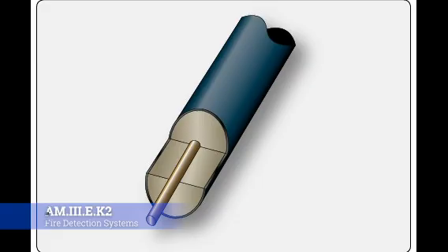All right, so first off, we understand that the way that this thing works is that the salts that are in between the outer sheath and the inner wire basically get hot, and as they get hot, their electrical resistance decreases, causing the circuit to basically jump like that from the center wire to the outer wire. All of a sudden they start to have conductivity because it's running through that eutectic salt. This completes the circuit, sets off all the bells and whistles.